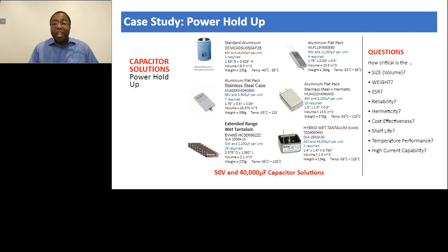This slide outlines possible solutions for our 40,000 microfarad 50 volt capacitor requirement. As we evaluate these options, we must ask ourselves the questions you see on the right. How important is the size and weight of our capacitor solution? How will the ESR impact the capacitor's performance? What are our shelf life needs?